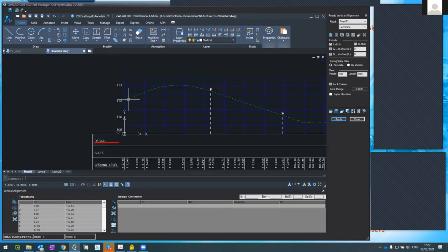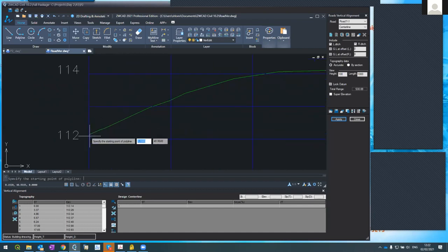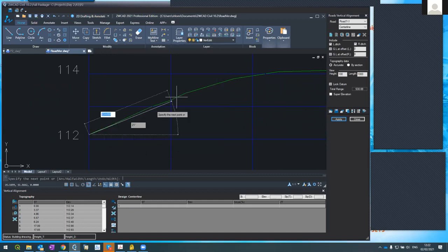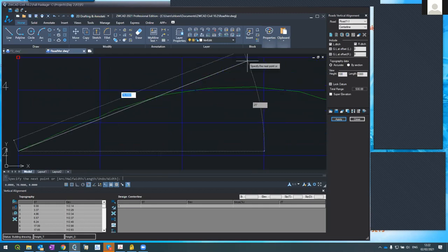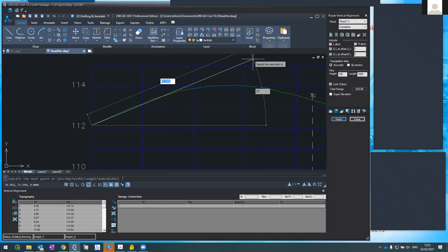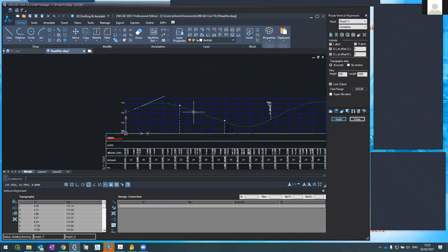Remember, it has to be a polyline in the vertical edit layer. So I'll start by connecting, sorry. I'll remove the nearest and use endpoint. Start from here. Here I will go more or less like this, and I'll do the same.